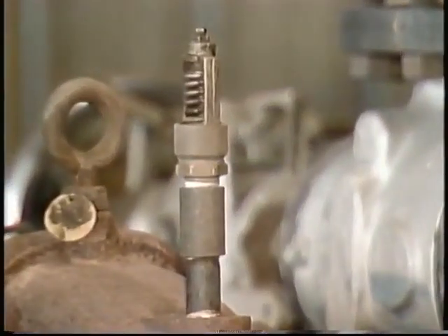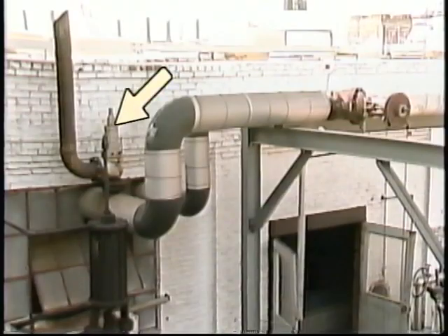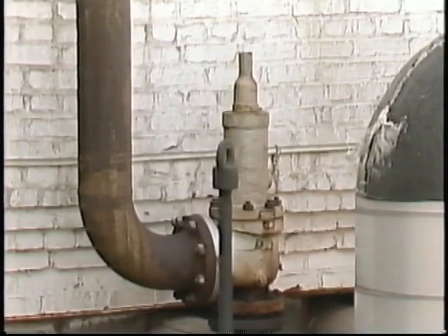Some turbines have a sentinel valve, as we saw earlier, that gives an audible warning when casing pressure becomes too high. And almost all turbines have a safety relief valve in the exhaust line that will open to protect against excessive pressure. If the safety relief valve isn't functioning, other corrective actions must be taken. You should check your facility's operating procedures to find out how this problem should be handled for the turbine you're operating.